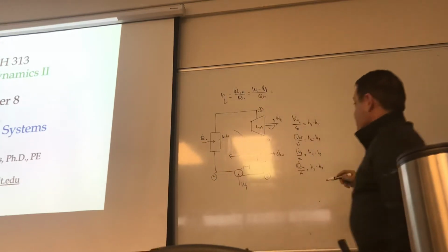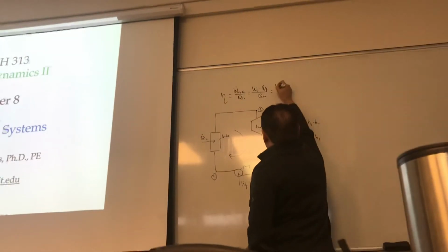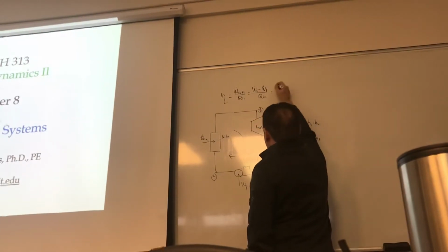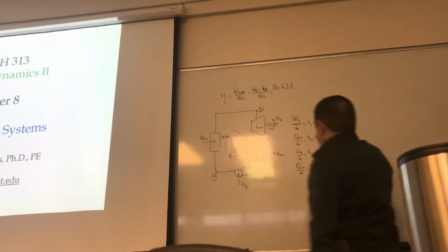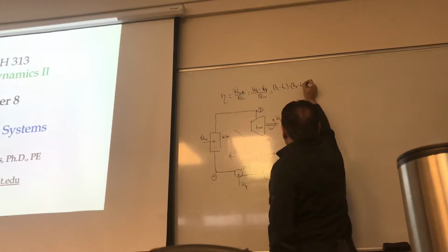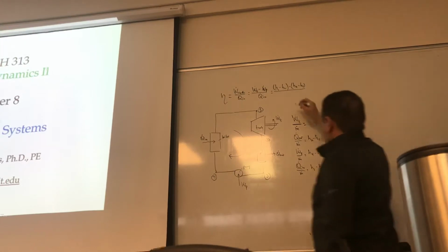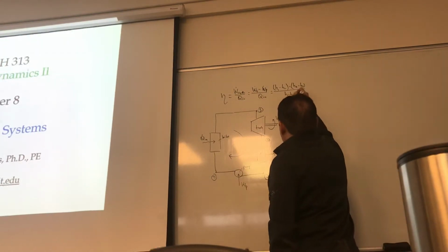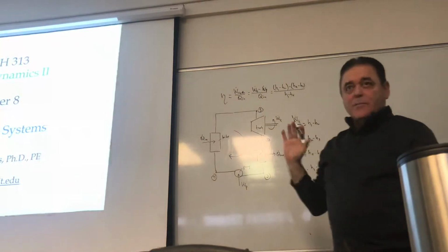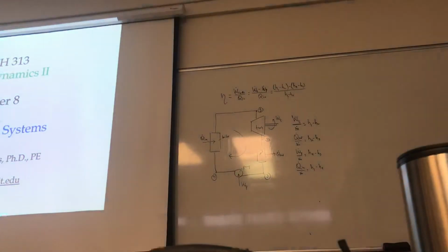So the equation then becomes, what is WT? It's really H1 minus H2 because the M dot cancels out, right? Minus WP, which is H4 minus H3, divided by Q in, which is H1 minus H4. You see, all those equations that may have looked complex, really, if you draw the cycle and then just use a little bit of common sense, you could actually reproduce all those without any problem.